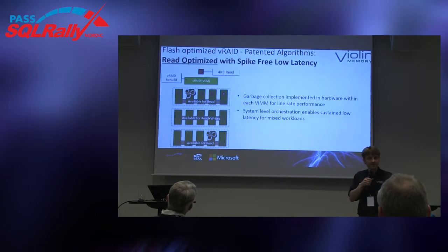In a traditional SSD, if an SSD is busy doing this housekeeping, it will block any reads, block any writes. So it's not only a write problem, it's also a read problem when this process is going on. And then the next module down here is available for both reads and writes, and this one is available for read. And in our arrays, we have 4 of these sections. So we can keep on writing for hours and hours with full bandwidth.